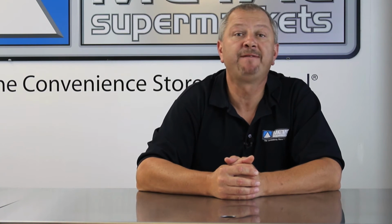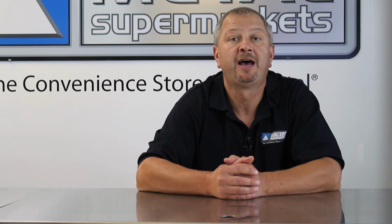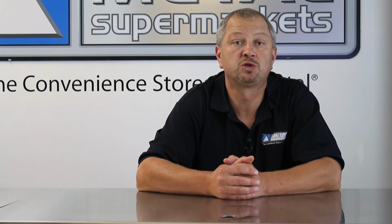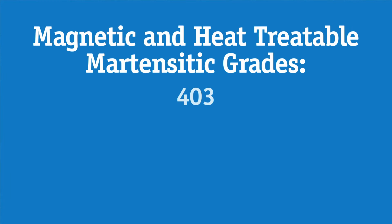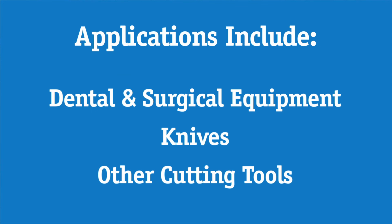Martensitic steels contain 11 to 17% chromium, less than 0.4% nickel, and up to 1.2% carbon. The higher carbon content of this heat-treatable steel affects forming and welding. To obtain other useful properties and prevent cracking, preheating and post-weld heat treatment is required. Martensitic stainless steels such as 403, 410, 410 nickel molybdenum, and 420 are magnetic and heat treatable. They are often used for dental and surgical equipment, knives, and other cutting tools.